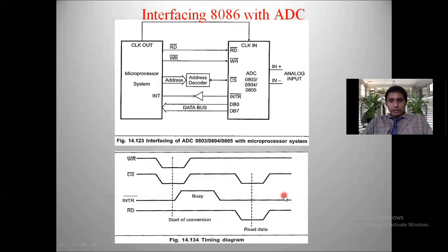So whenever conversion is completed, what happens? Now we are activating the read bar signal here. The read bar signal is now low whenever data is available, nothing but conversion is completed. Like that we can analyze how the pins are enabled or disabled as per the requirement.